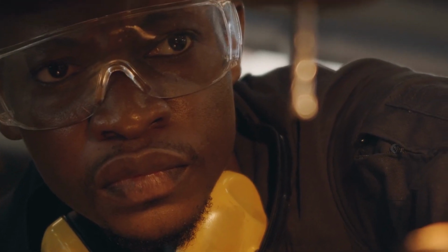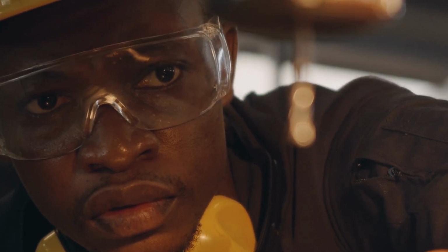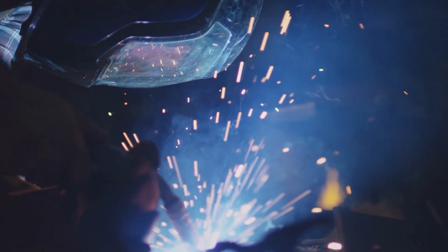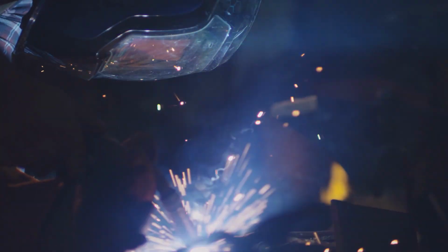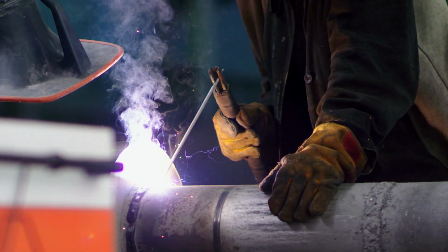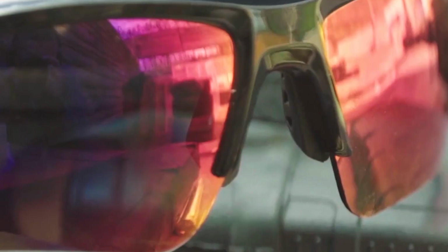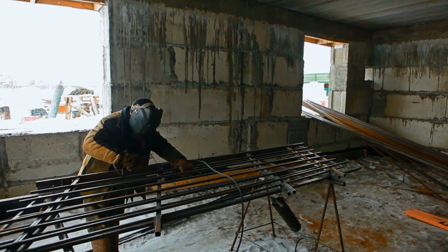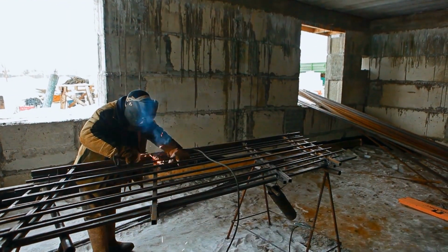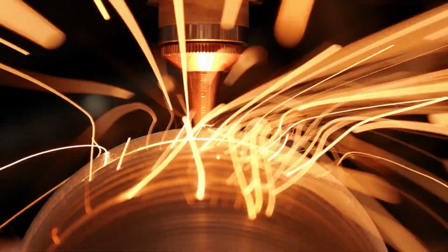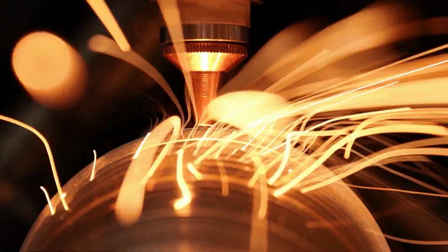For those wearing prescription glasses, your protection should either have the prescription built in or fit comfortably over your glasses without disturbing them. Now, if you're working with harmful light radiation, like welding or lasers, additional standards apply. For instance, welding operations require varying shades for the welding filters depending on the type of work being done, while laser work requires special safety goggles specific to the laser wavelength being used.